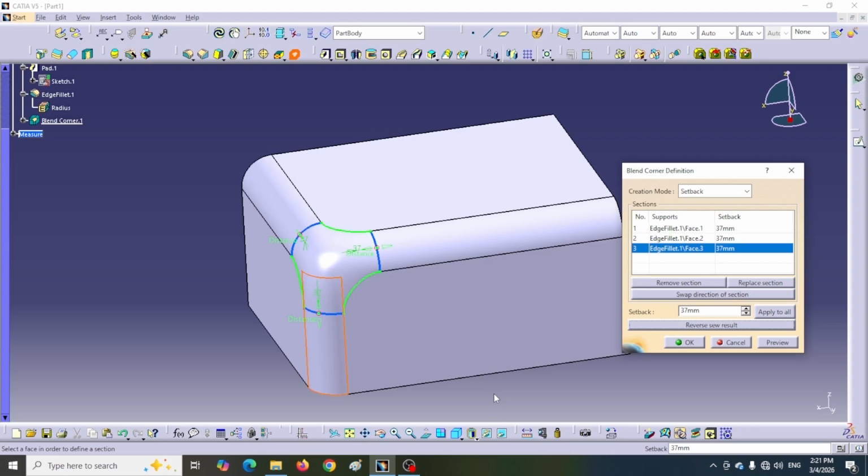You will see the cube displayed alongside the blended surfaces. This option reverses the normal vector of the final surface. The surface normal direction is used in later operations like trim or thick surface. If the direction is wrong, later operation may fail.